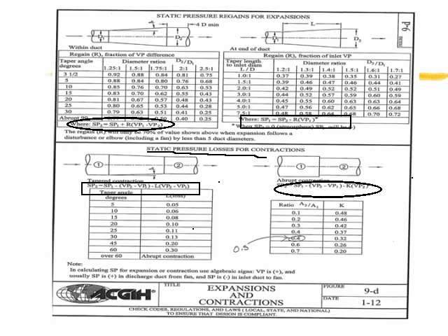So all we're doing with that formula is accounting for the change in static pressure by having a contraction in our system. So we came up to the contraction with a particular static pressure loss, then air moves through our contraction, and we should have an even higher static pressure loss. And so is the contraction gradual with an angle, or is it abrupt? If it's abrupt, we take the area of 2 divided by the area of 1 to get our loss factor of K. And I scratched out 0.4 on this table and wrote in 0.5 because that's an error within your textbook.